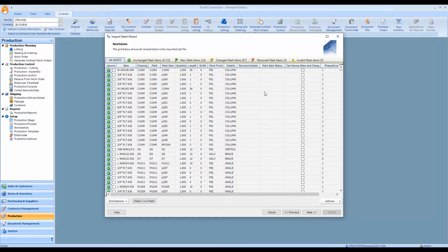So the process we're embarking on right now is the changeover of 3 columns and their associated base plates for a shorter column across the board, across all 3, and we're also exchanging the material on the base plates from 3/4 inch plate to 1 inch plate.